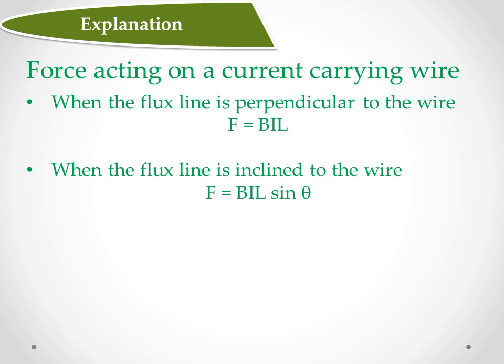Explanation. Force acting on a current-carrying wire. When the flux line is perpendicular to the wire, F equals BIL. When the flux line is inclined to the wire, F equals BIL sin theta.